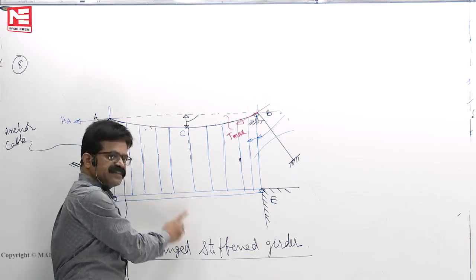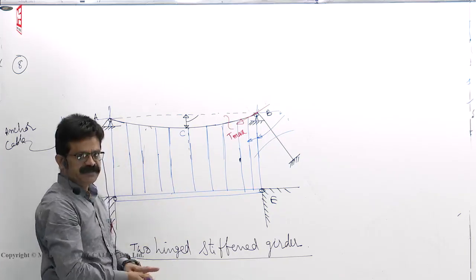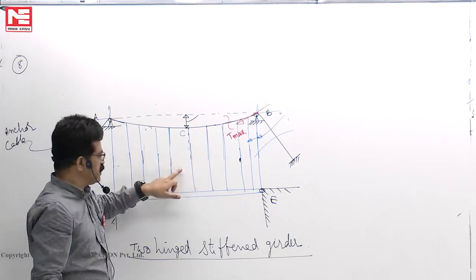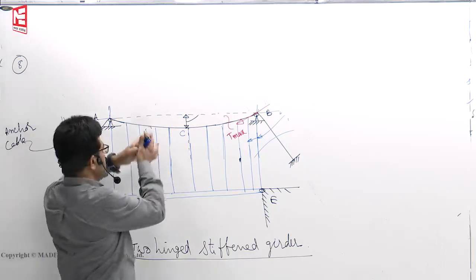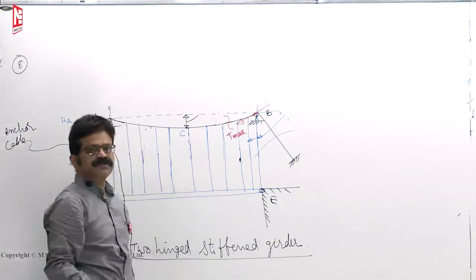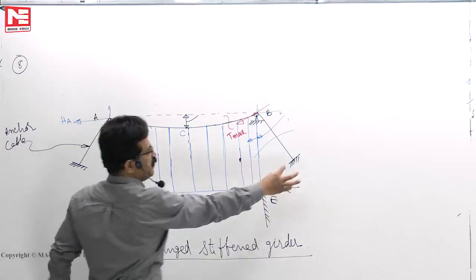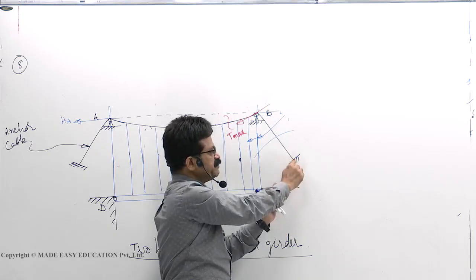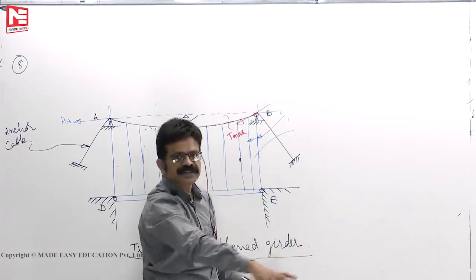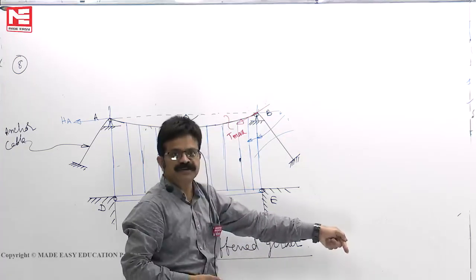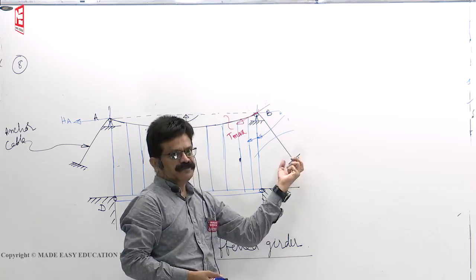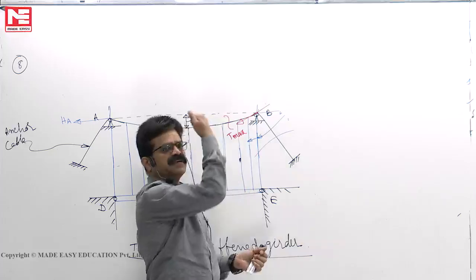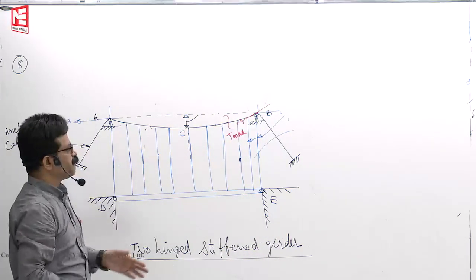So, to reduce the deflection in the beam, to reduce the bending moment in the beam, what we do is throughout the length of the beam we support hangers, we keep the hanger bars. These hanger bars are attached to a cable and that cable passes through pulleys and they are embedded here. Actually, there is a concrete block. This fixed one is a concrete block whose length can be 3 meters to 4 meters and this cable is embedded into this one, that male and female cone Freyssinet system or some system, you will pull them, hold them so that it will not come out. Here also same thing. Okay.